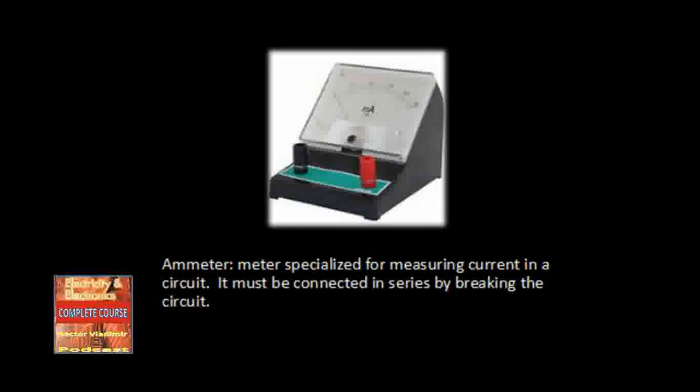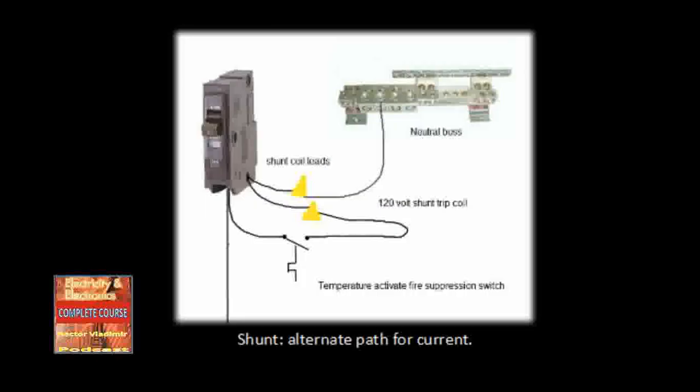2.2 Ammeter. An ammeter measures electrical current in a circuit. The ammeter will usually measure in amperes, milliamperes, or microamperes, depending on the scale design of the instrument. The coil in the meter movement of an ammeter is wound with many turns of fine wire. If a large current is allowed to flow through this coil, the ammeter will quickly burn out.